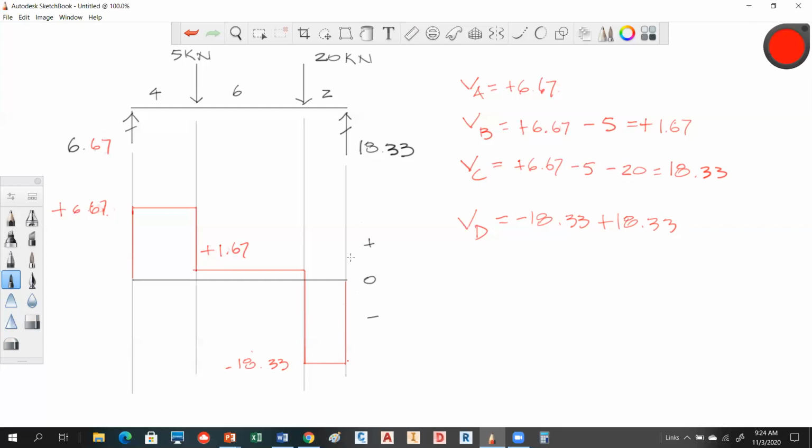Yeah. Where's the point of maximum shear here? It's kind of a loaded BC. Well, yeah, but if you look at that, Jacob, it's kind of a loaded question. There is no point of maximum moment because look at this. This whole range of the beam stays at what? It stays the same, right? So there's no point of maximum moment. What there is a range of maximum moment. I mean shear. I apologize. Maximum shear, okay? There is no point of maximum. You don't typically get a max point in shear. You usually get a range of values. Does that make sense now?